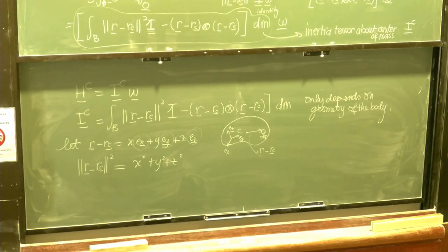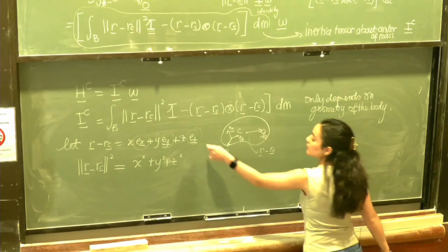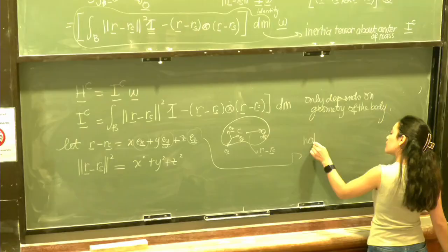Yes, the rigid body is moved relative to a co-rotational basis. If I put a basis fixed to me, the mass distribution relative to this basis is going to be constant, right? But relative to some other fixed basis it is going to change, right? So we're going to see that the components of the inertia tensor on a co-rotational basis are fixed, whereas on a fixed basis somewhere else in space they are not going to be fixed. So the components of this vector, and we'll do this.